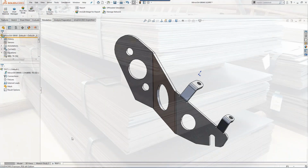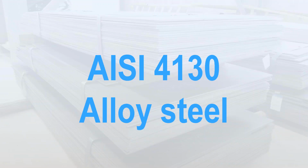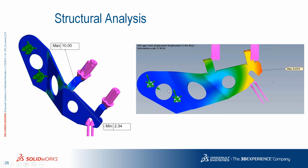In order to do that, it's very simple now. So URB designers changed the material to AISI 4130. It's an alloy steel. And in a couple of seconds more, just updating the analysis, they could reach a minimum factor of safety of 2.3. So the factor of safety is now good. The component is behaving as intended, and they avoided producing any prototype at all.